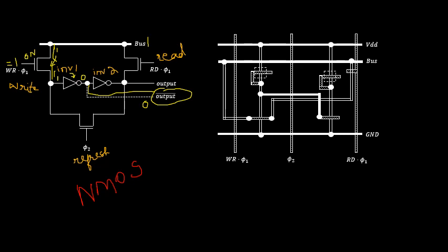So the reverse of that is being obtained over the output side. Now, if there is a presence of a capacitor, that particular value will get stored in the capacitor. If I want the exact same value to be returned to the capacitor, then I am using the output 0, which has to be cascaded with the second inverter, and that 0 is passed into the inverter 2 as the input, and the output obtained will be equal to logical 1 state. So here I will be obtaining the output exactly similar to what input I have applied. So the capacitor will be storing the charge in the form of a logical 1 state. This is how I am going to perform the write operation.